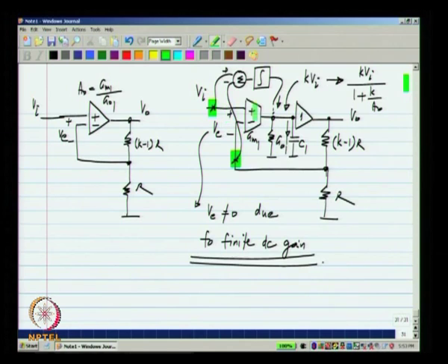It almost looks as though the first one reaches steady state and based on the steady state value we inject some current here. Okay. In reality, what will happen is, the original one is going through its integration and this is going through its integration all simultaneously. It is just that this integration has to happen slowly enough, so that it appears as though the first one, the original loop has reached steady state and you are measuring the steady state error, based on that injecting a current into G0. Okay. We will see the details of that in the next class.